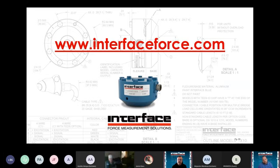So oftentimes you're better off going with a larger sensor. Pay attention to the actual output. That's one advantage of most of our products, especially in the LP ranges. We offer 4 millivolt per volt output. So you may be thinking that jumping up to a higher capacity is going to sacrifice resolution or signal, but you need to look at how much electrical signal you're getting. If you're comparing a 4 millivolt per volt larger capacity unit to something that may only be 2 millivolt per volt for a lower capacity, you may be just as far ahead, but with significant safe overload on top of that.